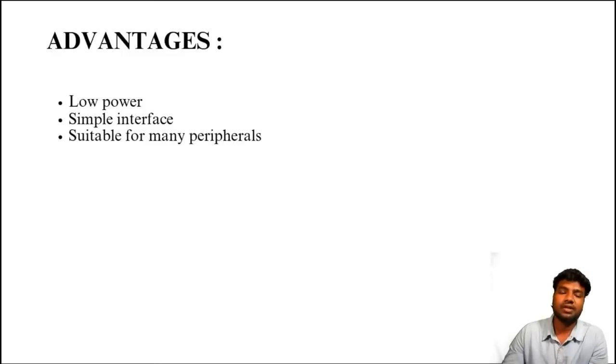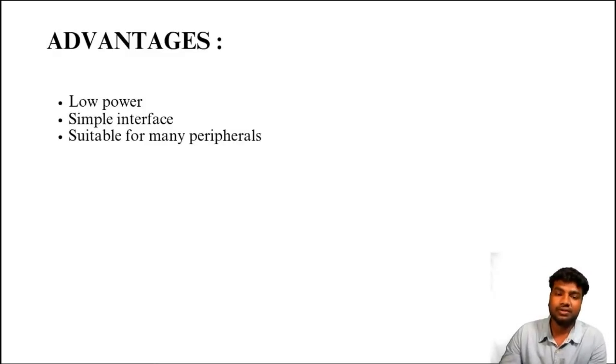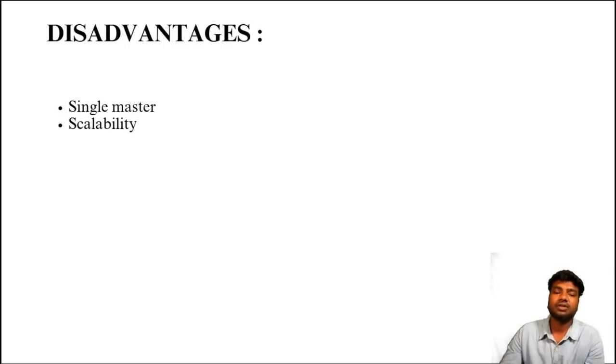So these are the advantages of the APB protocol: low power and a simple interface, suitable for many peripherals. And this is the disadvantage of the APB protocol: single master, so limited scalability.